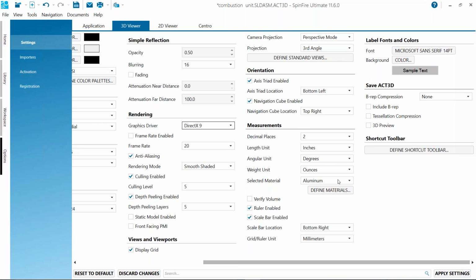We have to change that from the default auto setting on about half of our computers because of the age of our machines. Do you? Yeah. What have you been setting it to? Actually, I just throw back to OpenGL. Okay. Yeah, and again, sometimes that's fine. And some computers I have to set it on DirectX 9 because OpenGL doesn't.